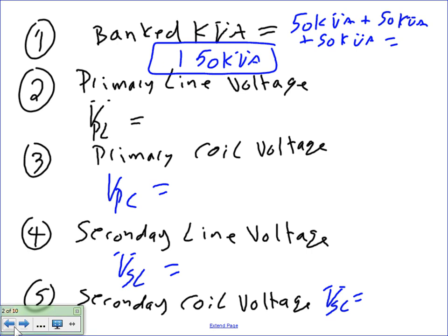When you buy the transformer, for the most part, other than voltage, you really don't worry about how it's hooked up. Most of the time you have delta-Y. But you could go Y-Y. And the only difference is the conductor will be bigger or smaller when you size them. I'm referring to the coil conductors.